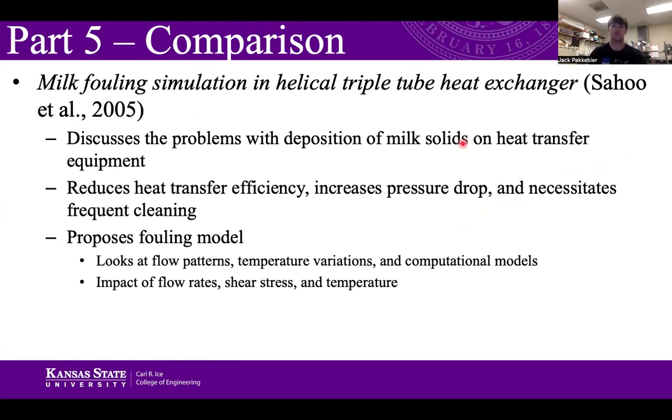Then for the final part of the presentation, we'll look at comparison from that initial paper that I considered. Milk fouling simulation in a helical triple tube heat exchanger, Sahu et al. 2005. They discussed the problems with deposition of milk solids on heat transfer equipment, where it reduces heat transfer efficiency, as we've seen, increases the pressure drop, and necessitates frequent cleaning to keep up the efficiency of your pasteurization setup.